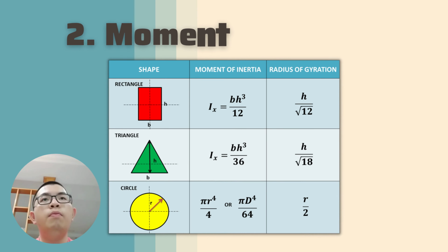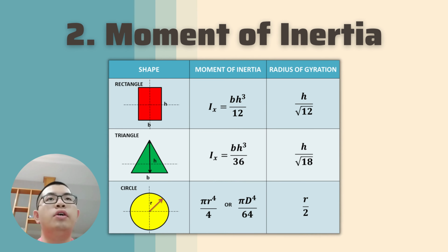In physics, the moment of inertia is a quantitative measure of a body's rotational inertia. That is, the resistance that the body exhibits to having its speed of rotation along an axis altered by the application of torque. The axis might be internal or external, and it can be fixed or not. The moment of inertia, on the other hand, is always expressed in terms of the axis and is defined as the sum of the products produced by multiplying the mass of each particle of matter in a given body by the square of its distance from the axis.